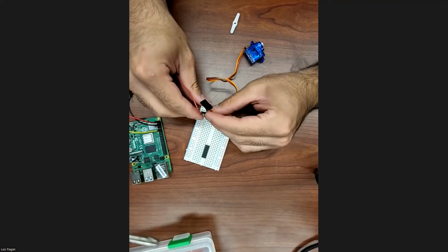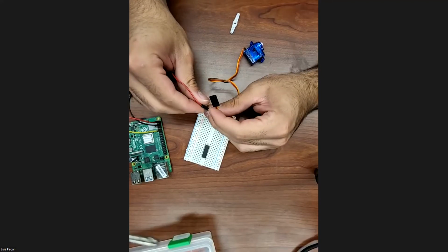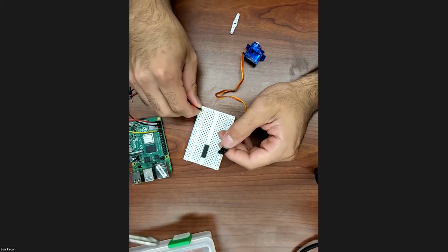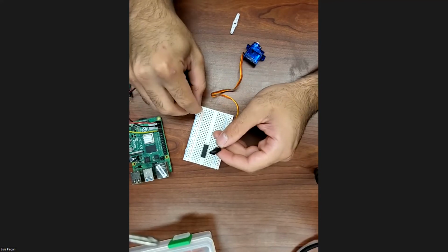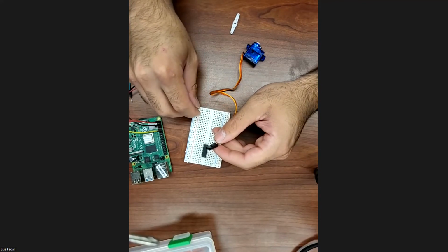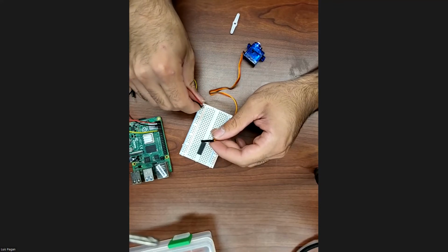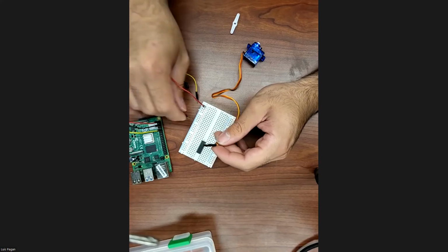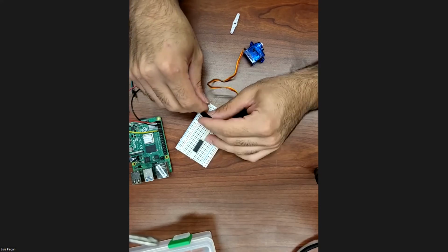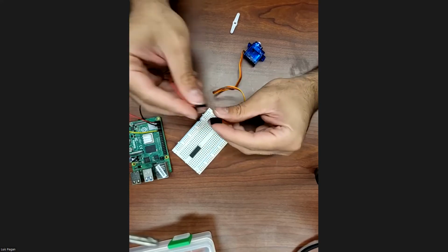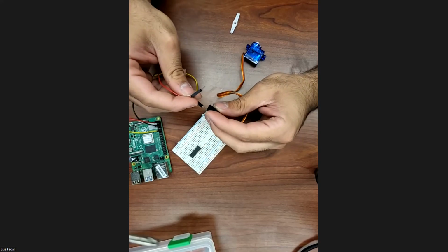When you do have to control more than just one servo, let's say you're also controlling the H-bridge and whatnot, you want to make sure that you connect it to the breadboard. Otherwise, you won't be able to supply power to more than just one device. But again, for the purposes of this demonstration, it doesn't really matter since we're only doing one thing at a time. So I'm just going to plug in ground to the brown cables.